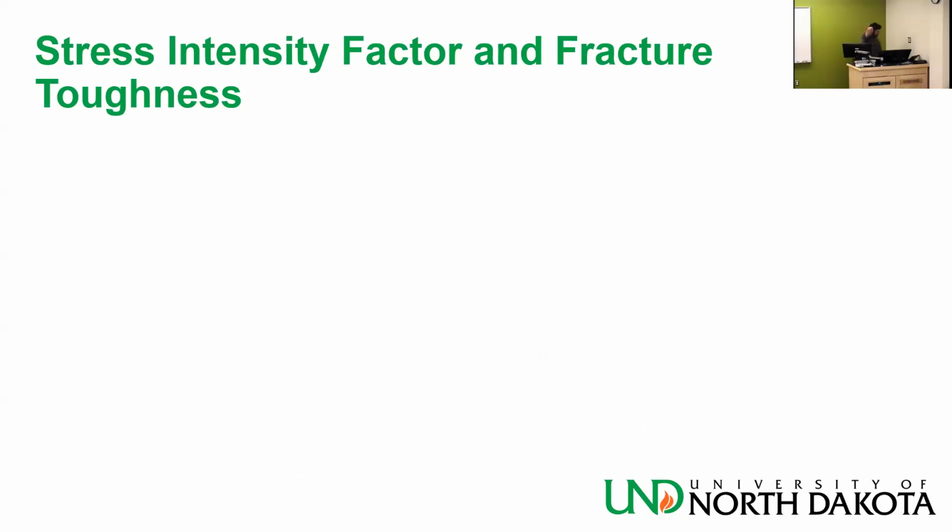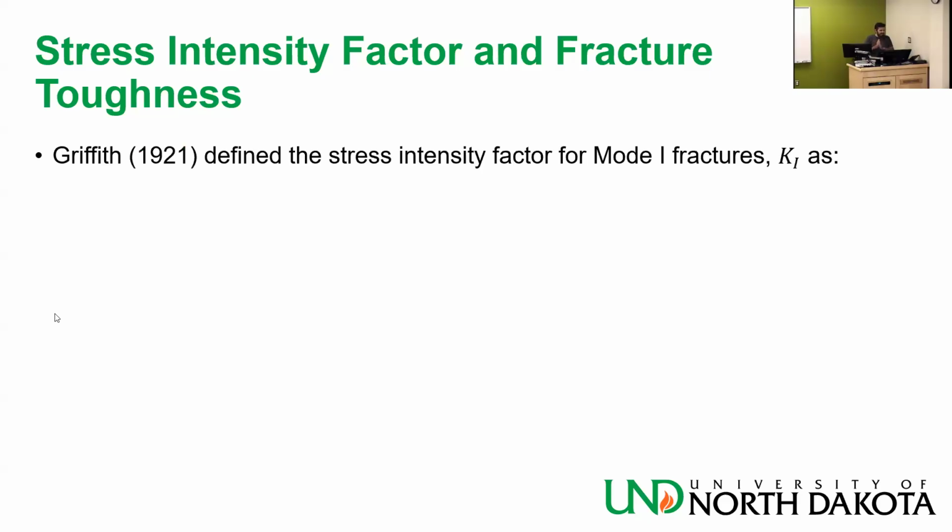Now, the most important outcome of that paper is the concept of something called the stress intensity factor or the fracture toughness. Well, critical stress intensity factor or the fracture toughness. These two entities that you have on your screen now are not the same, okay? If I put critical stress intensity factor, it's going to be the same as fracture toughness. And I will explain how it is. I will explain so that you can understand.